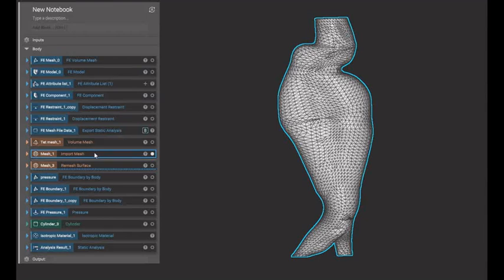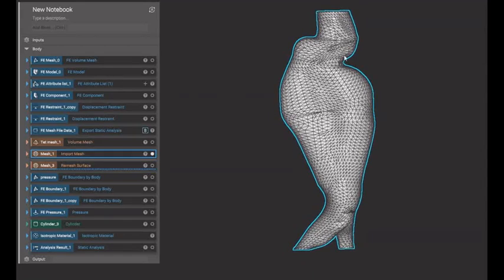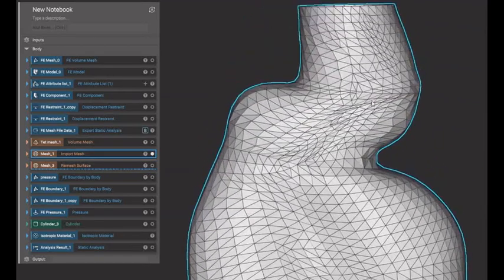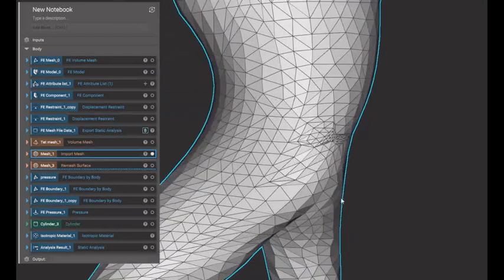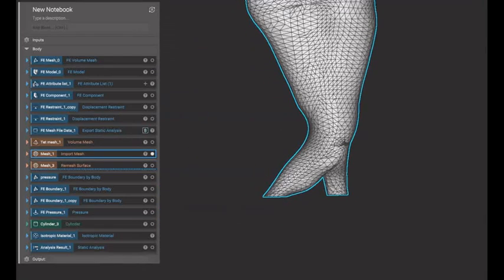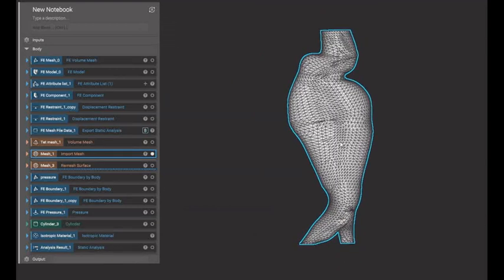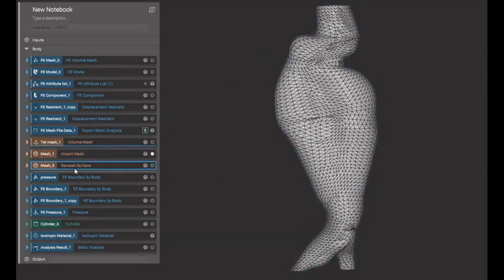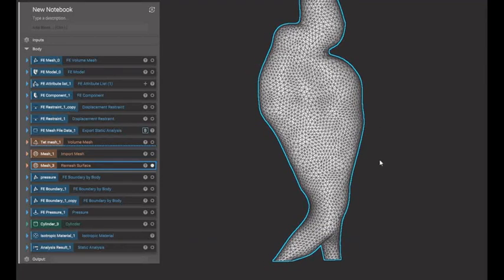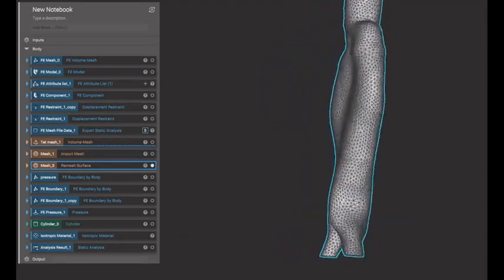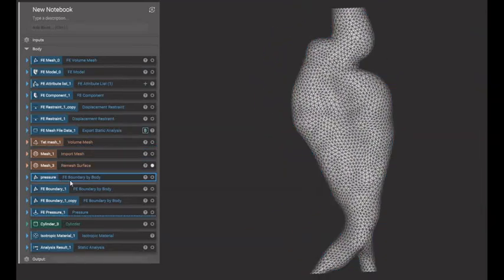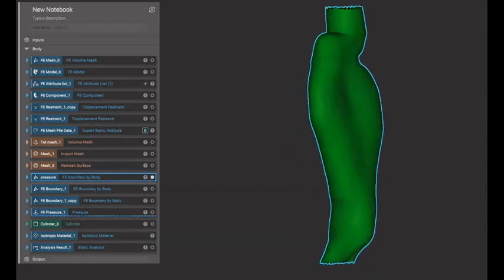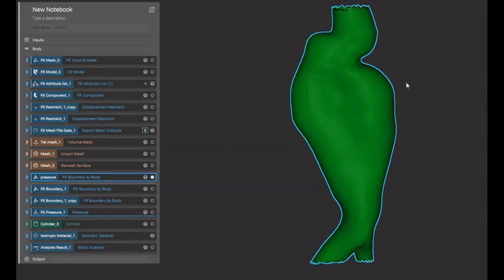The first step was importing the mesh, and this is the mesh you actually get of the deformed aneurysm, and you can clearly see that there are a lot of irregular mesh parts that will not be able to provide any processing for the computational fluid dynamics analysis. So what we had to do was remesh it, and here you can see a more symmetrical mesh that provides us with enough faces for the pressure correction. Here you can see the faces in which the pressure is going to be applied.